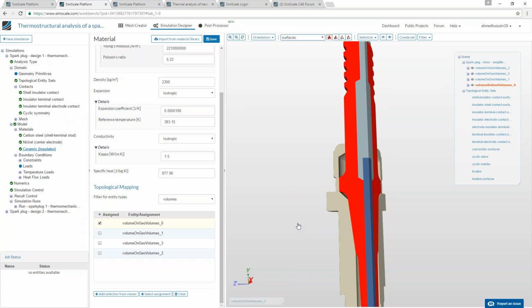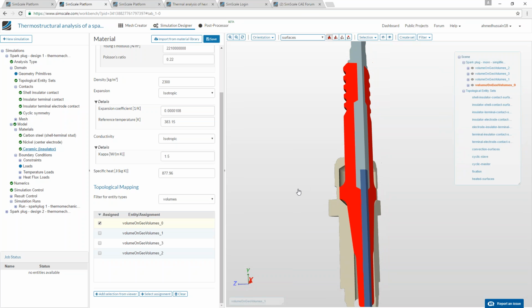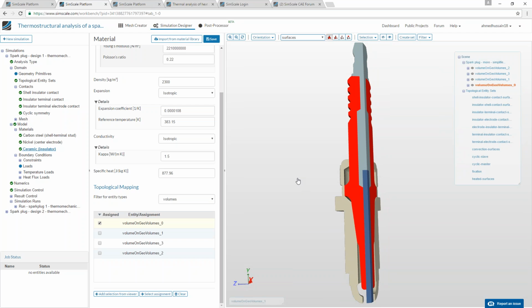But other than that, you can define some refinement zones, for example some faces or some volumes, where you define a refinement level that will then be followed. So that is the difference. You can define manually where you want to refine the mesh and where not.